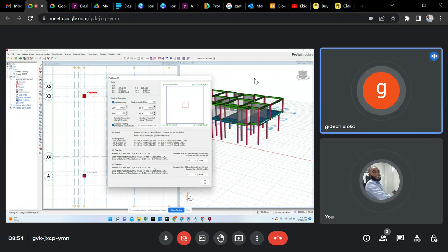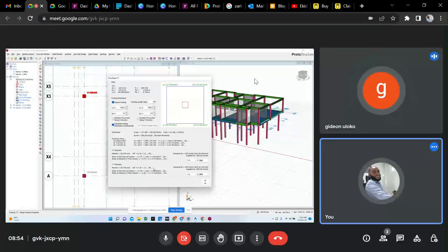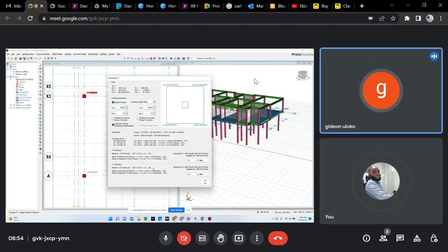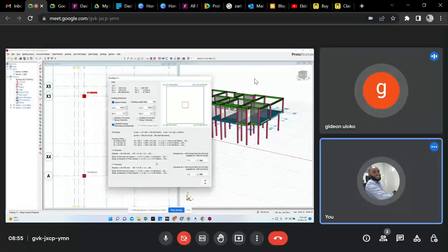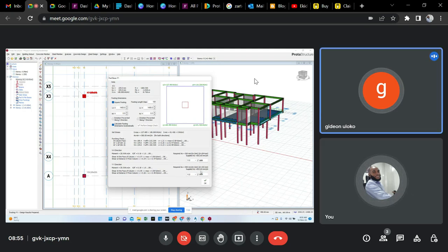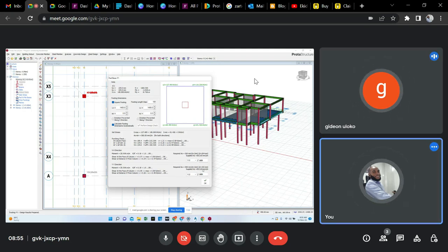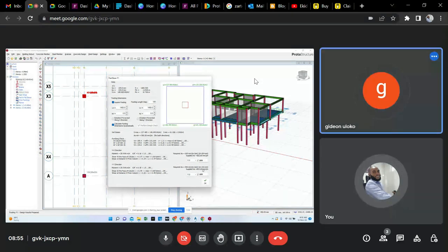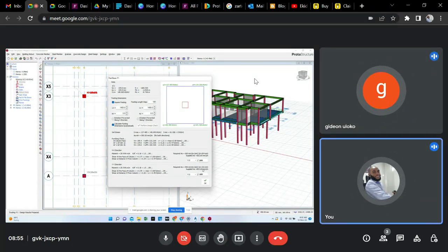Then this place also shows steel bar area, which has 225 spacing or other spacing; that is your reinforcement spacing. On this other side, the minimum spacing that you're going to allow is at least 125 or 100. But I always say you should allow 125. That is the minimum spacing of reinforcement that you're going to allow.